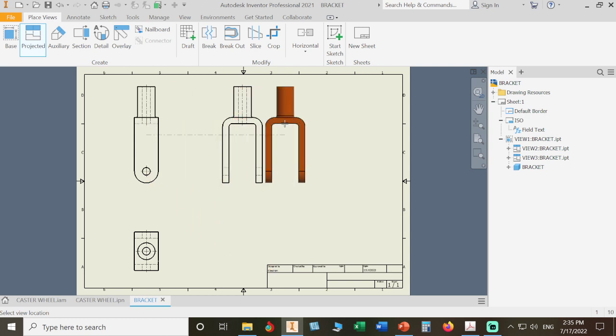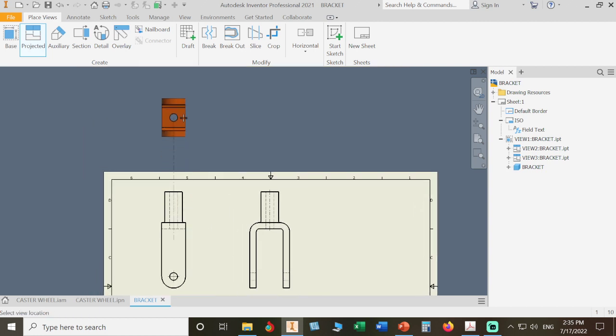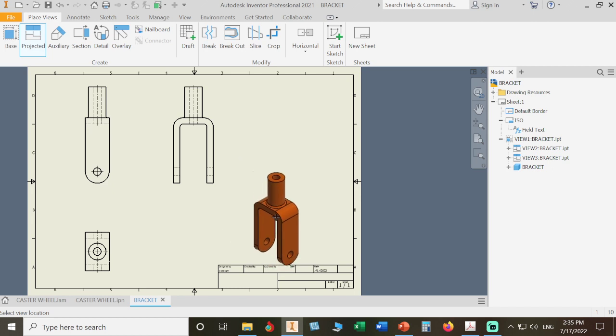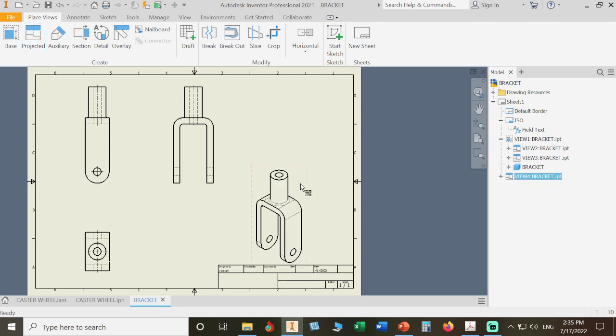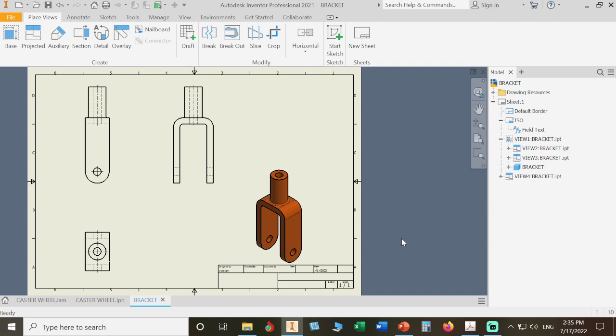Okay, horizontally we'll have left and right side. Vertically we'll have the top view, bottom view if you go up. But if you need an ISO view, you have to go diagonal, click, right click, create. Usually we make this shaded in order to show the part, etc.